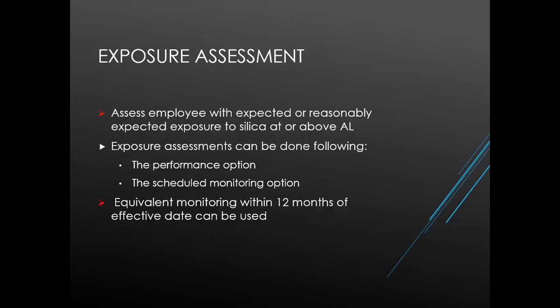Employers must assess each employee's exposure to silica who is or may reasonably be expected to be exposed to respirable crystalline silica at or above the action level. And this exposure assessment can be achieved in one of two ways, either by means of the performance option or the scheduled monitoring option. Let's take a look at these two assessment options.